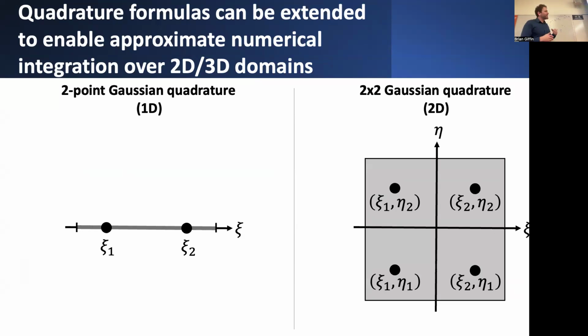And in doing so, I actually ensure that even though this domain is much more complicated in 2 dimensions, it gets worse in 3 dimensions. Assuming I choose a sufficient number of these integration points placed at these strategically chosen locations and weighted by these appropriately chosen integration weights, I nonetheless ensure that I'm going to be able to exactly integrate polynomials over this square patch, let's say, exactly, which is incredibly powerful.